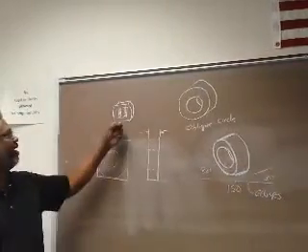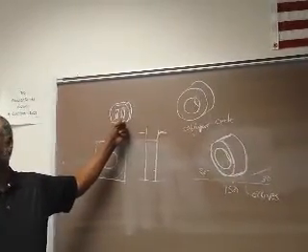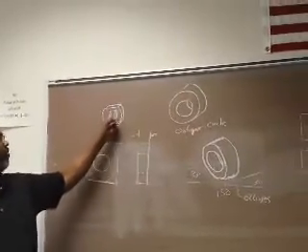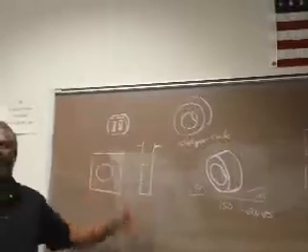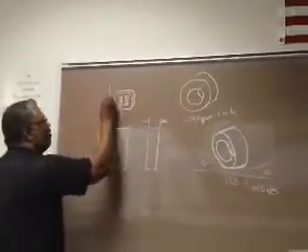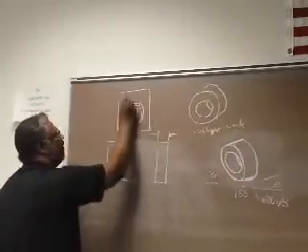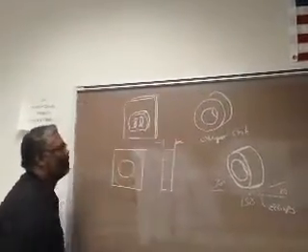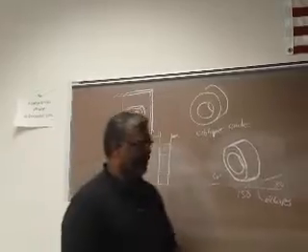But to draw it as an oblique would be easy because you already got the orthographic view. You just copy it back, connect your line, show these thicknesses, and there's that portion of your outlet there. See, it's a little bit easier to do it as an oblique.